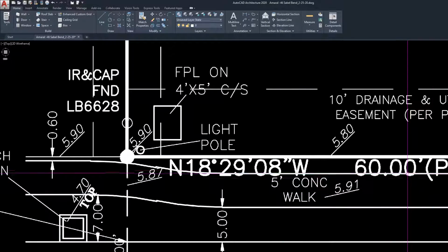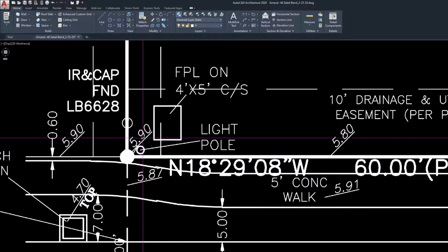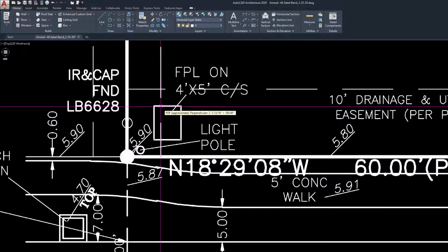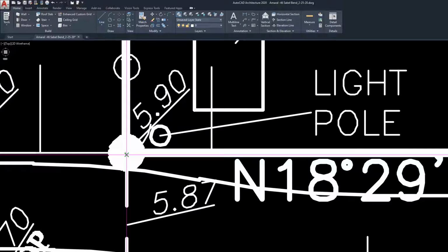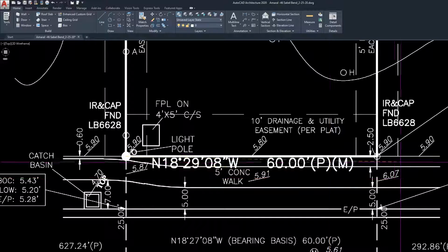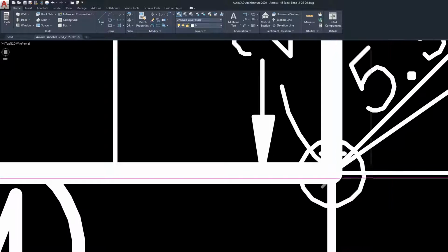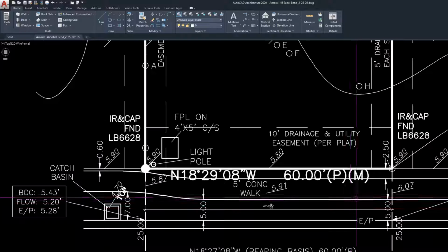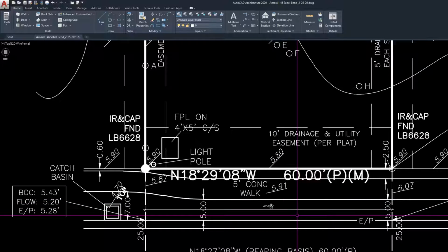This dimension line we're looking for is 60 feet. Click on your dimension and you can see right away it starts to pick up little grip points. So this is awesome, and when you have one of these PDFs, it's way more accurate. So we can click on the intersection of these two lines, or what we assume to be the center of the circle. Same thing here. Now when I brought it in, it only came in at 47 feet.